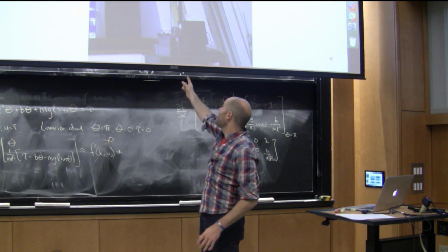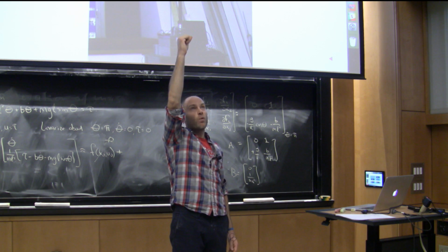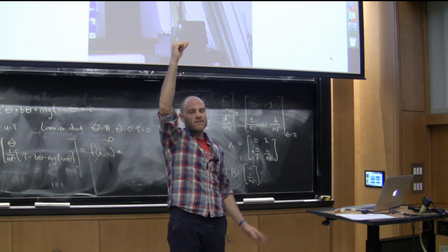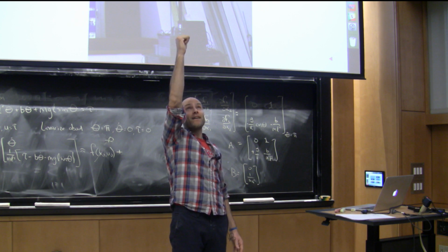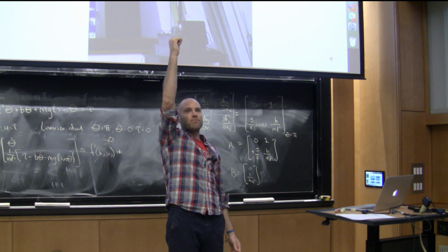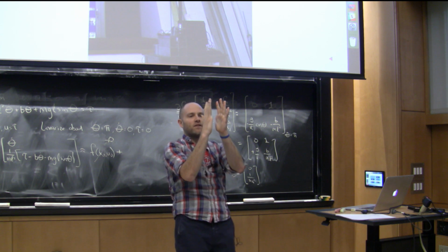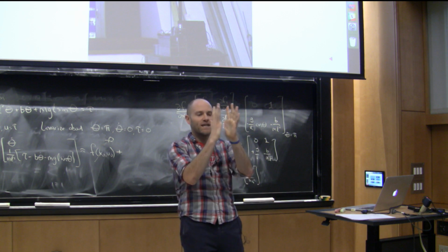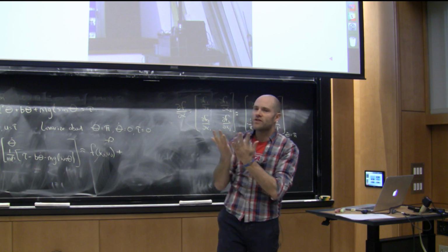And you could also, if you think about the system as passively stable like this, right? In the equations. Okay, but if I ran a wire a little bit much to the left, or if my encoders were offset, there are encoder discretization errors, but that's super small because we have crazy encoder ticks, okay? But the system is actually not probably passively stable when my encoders read 0, 0, because I have some encoder calibration error, but also because the system's just not perfectly balanced, right? We can sit there and balance it. That's typically how when we're programming it, we'd sit there and go like this, turn it on, and you'd kind of run away like that. So it is possible to balance it, but it's not perfectly aligned when it's balanced, just because we're not perfect.